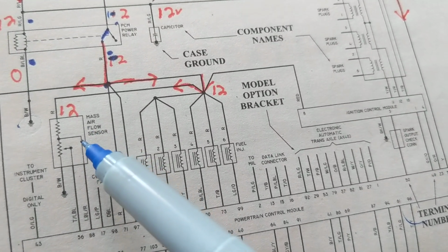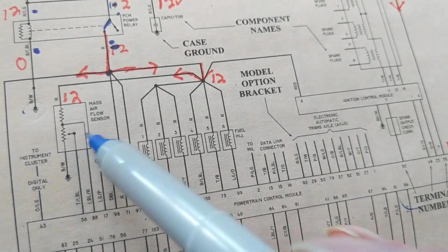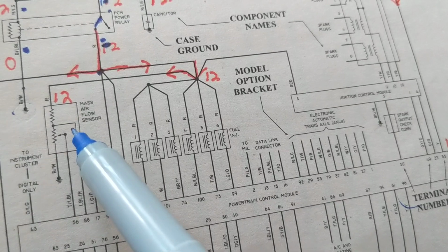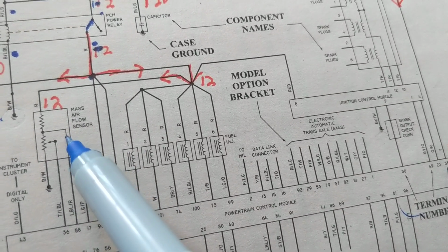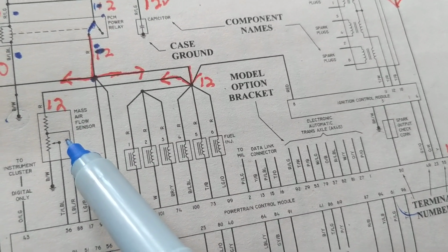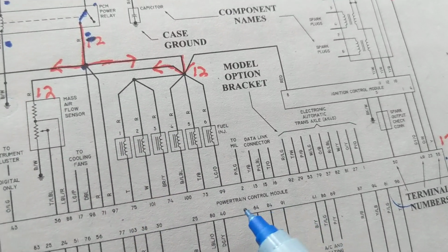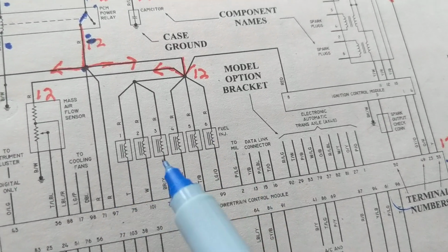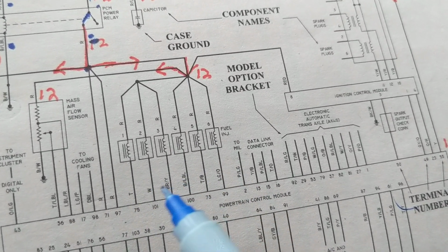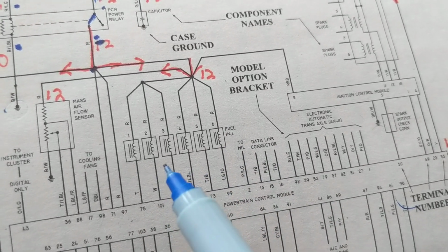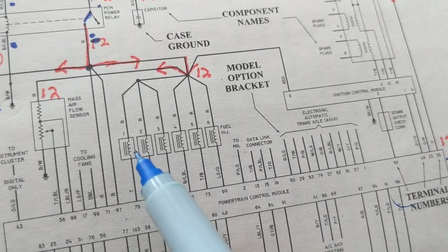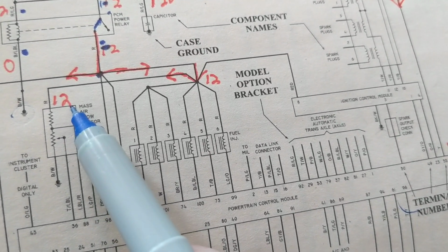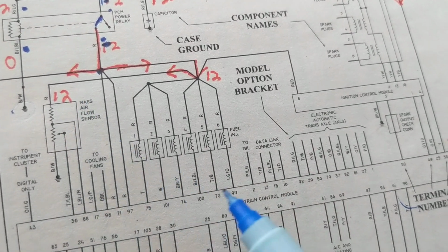I express one thing. Always try to get the part from the dealer. Why? Because this has to be precise. In order for this to be precise, this electronic component has to be correct. Okay? Remember, the powertrain control module looks at 0.01 volt, 0.02 volts, 0.03 volts, 0.05, and so on and so on. You cannot say, if I measured 0.5 and it's supposed to be 0.9, oh, that's close enough. That's close enough. No, not for the computer.